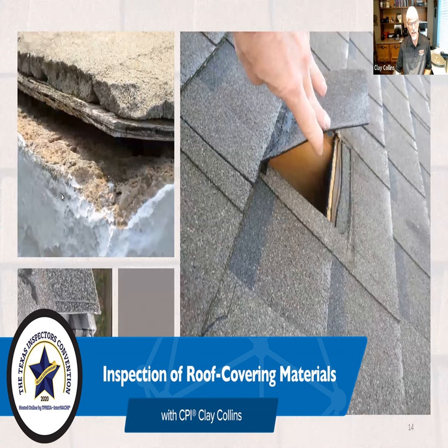This was a tall enough attic space that I could get over to some of those areas and take a look at it. A lot of times you only inspect from service decking, from that passageway, and it simply doesn't allow you to get back into those areas. So I would caution you to perhaps offer up a disclaimer that says, here is where I looked at the attic from. We're required to do that.